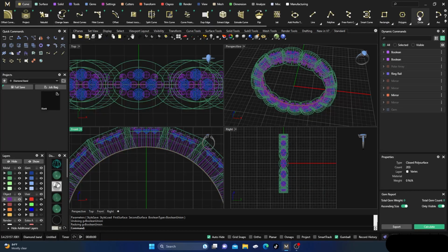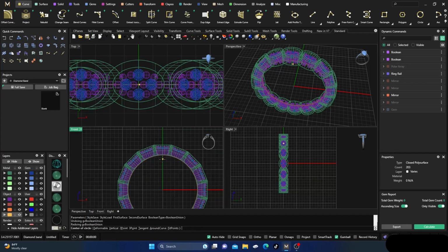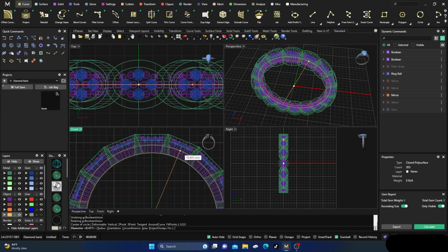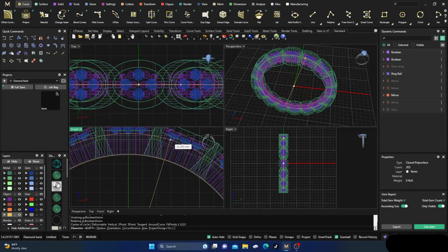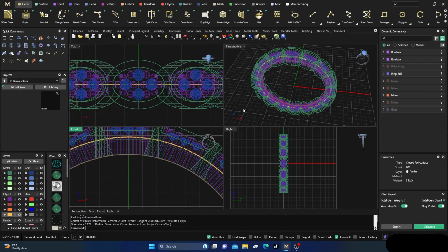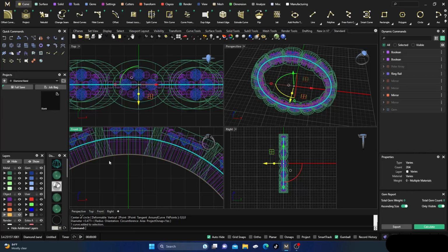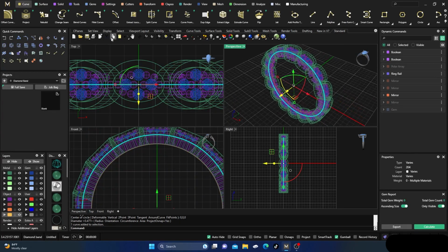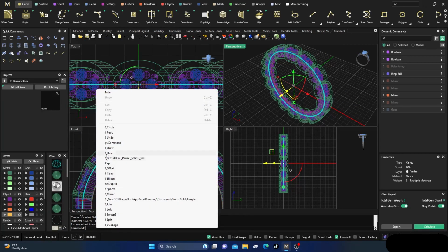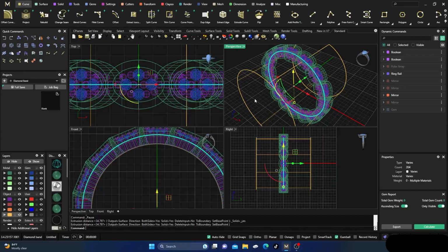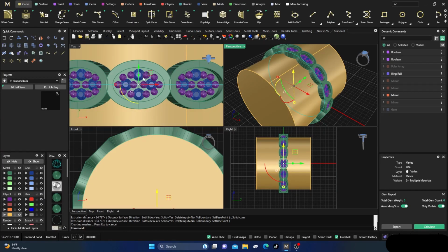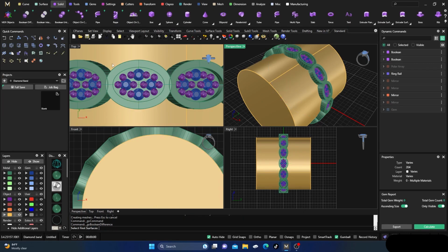Let's go ahead and grab a circle, and I'll switch to yellow, and we'll go here, and we'll just kind of, let's see, where's our bottom? Right in there. Take that yellow, right click here, go to extrude straight, and we'll just drag this out here. Give it some shading, and we'll do a Boolean difference just to get rid of those prongs there real quick.